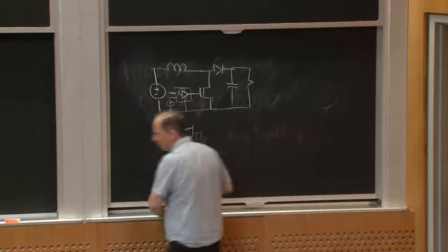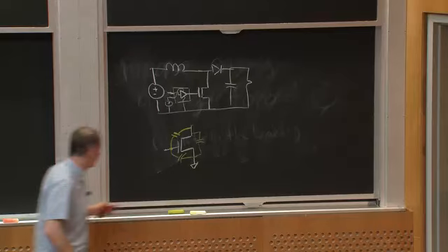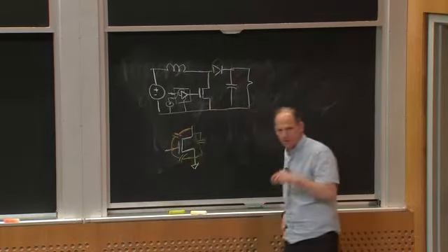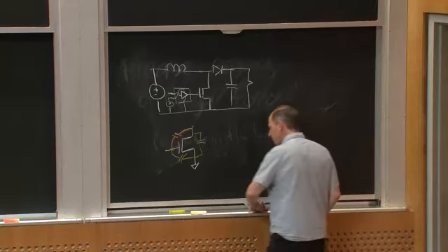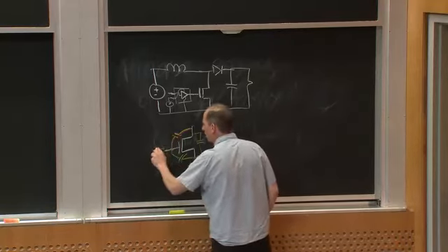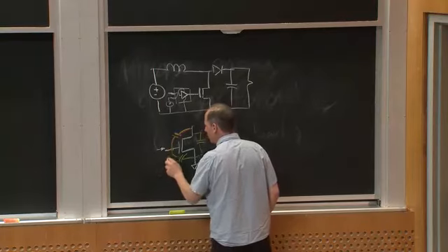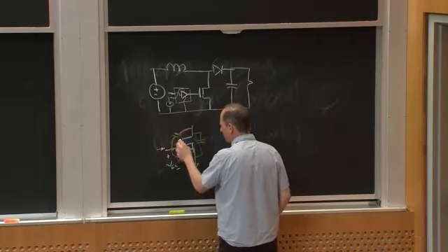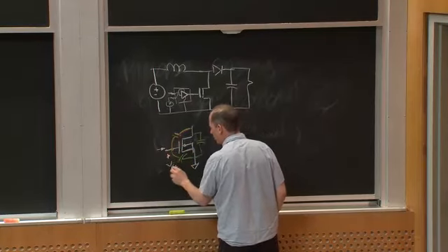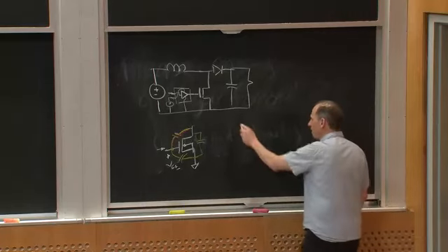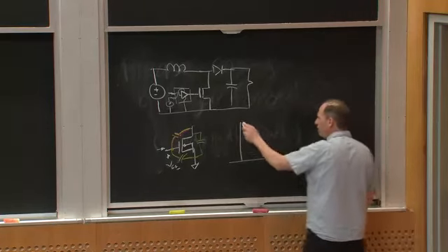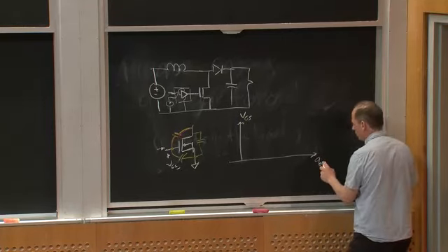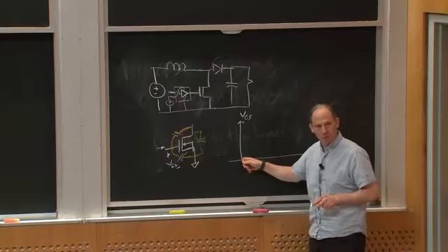So this capacitance is the so-called Miller feedback capacitance. This guy right here can have a big impact on the switching characteristics here. Because if I look at the charge I'm sourcing in here and the voltage VGS I'm getting, if this is an N-channel MOSFET, it's this VGS voltage that controls how it switches on. If I looked at VGS versus Q sub G, the gate charge I'm putting in, what would happen?